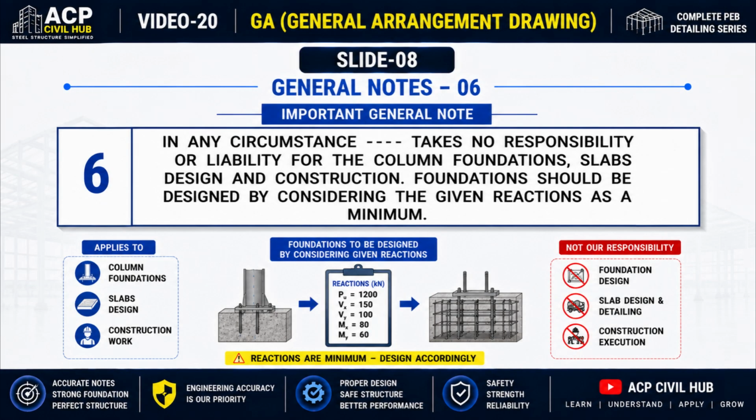Now let's understand General Note number 6. This note clarifies an important responsibility in every PEB project. It states that the steel building supplier is not responsible for the design or construction of the column foundations and concrete slabs. These civil works must be designed and executed by the project's civil or structural foundation engineer.